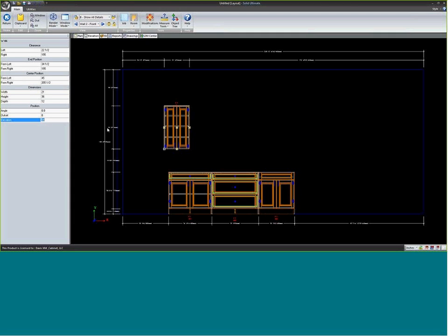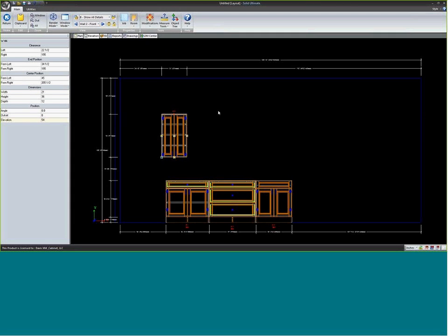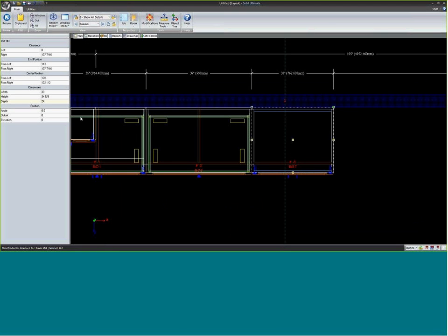Now, elevation. I can change it if I want a staggered look, if I want a small cabinet up here above a range or a fridge or something. I can change its elevation manually or make it stick above the soffit height too. All of those things can be customized by a combination of your height or your elevation settings. Your depth is pretty obvious. If I click on there, I can just change a cabinet to 30 inches deep.